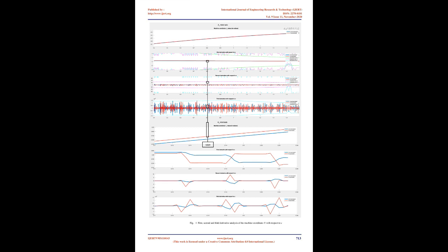Consequently, the vectors of velocity, acceleration, and jerk are denoted respectively. Evaluation of these functions can be done only after the trajectory planning. In fact, they are used in trajectory planning optimization, minimizing the total time needed to pass the entire path and keeping all feed, acceleration, and jerk constraints satisfied.